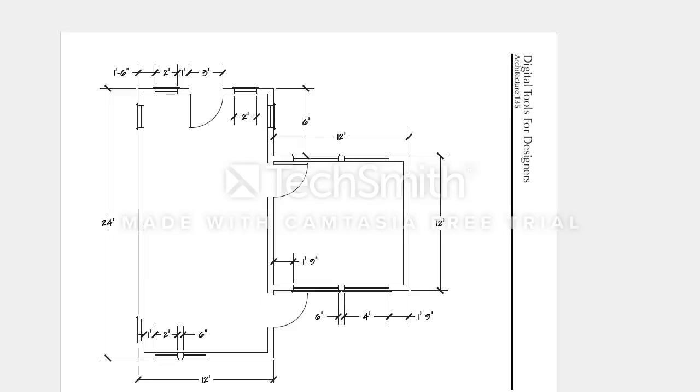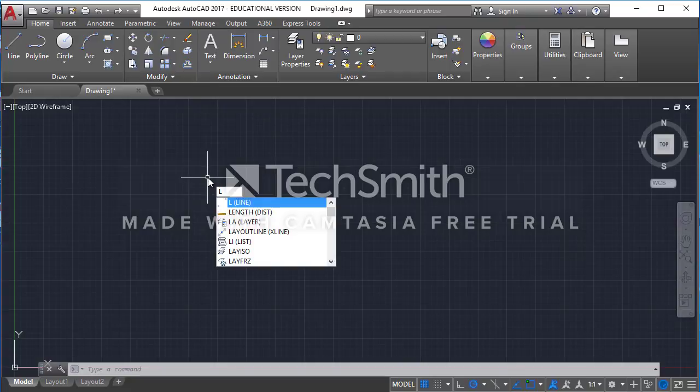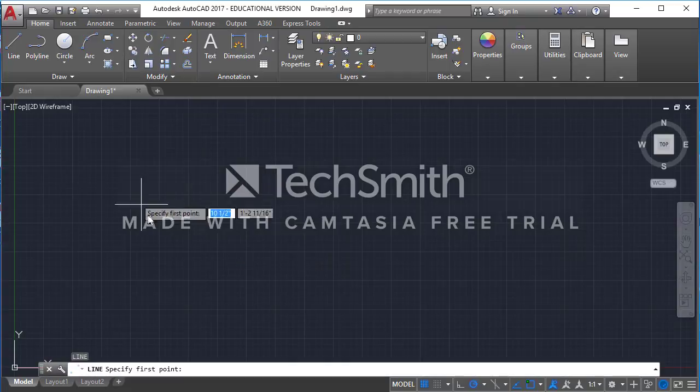Okay, so let's start to learn some of the basic commands here. The first one that we're going to learn is just the basic line tool. As I mentioned earlier, we're going to type in L. L is for line. You can also just type in line. The first thing that it asks you to do is to specify an insertion point.